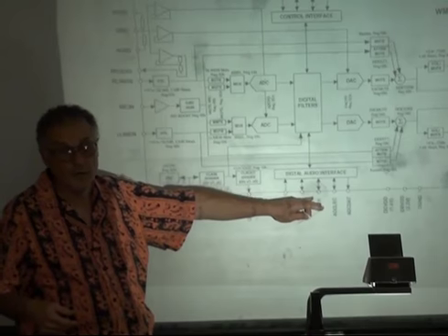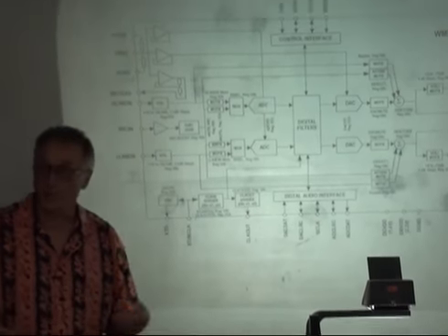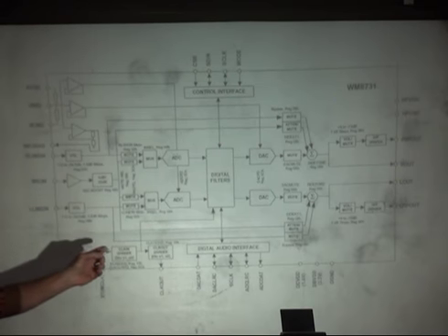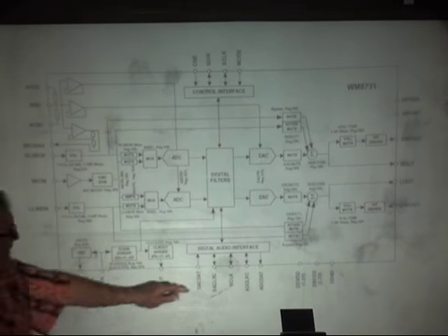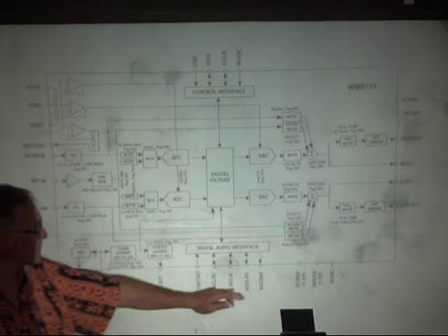Now you can redo that at any time if you want to make, say, a gain control on the left or right channel, but typically for these labs you do it once and then you don't mess with it anymore, except when your state machine running on the FPGA gets out of sync with the state machine running on the Wolfson chip, which happens moderately often. Then all of the high-speed data comes through these lines.